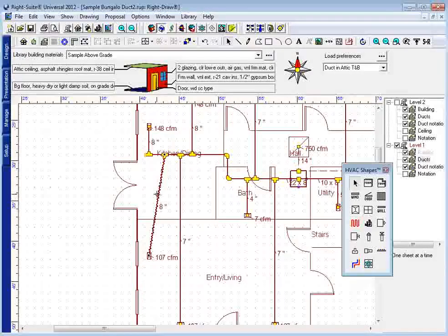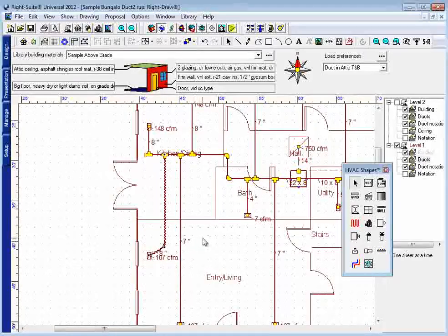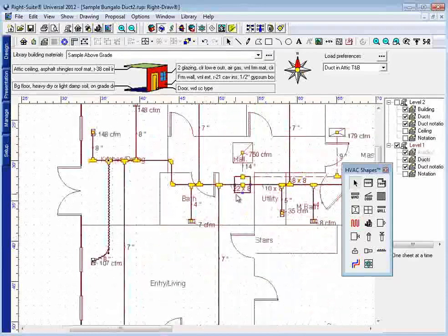And when I hover my cursor on the duct, I see my add edit point icon. If I hover my cursor somewhere along this duct, it doesn't really matter where, left click and hold and drag, I can bend that flex duct like so.